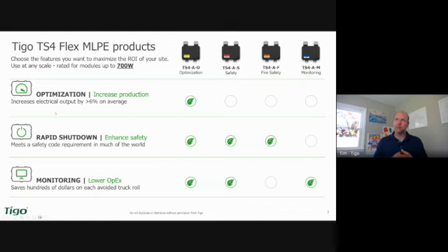That's the ability for each module to produce at its own peak performance, right? Sometimes a system will be installed in a string. If you have an inverter and let's just say 30 modules, you may have 3 strings or groups of 10 modules apiece. What can happen is when a single module is impacted by shading, or degrades over time, or gets heavy soiling, its efficiency will be reduced relative to the other ones on the string, and that one individual panel can bring down the entire string. By having optimizers, each module can produce at its own independent maximum production relative to the other modules on the string. And by doing that, on average, we see 6.6% more electricity by having optimization on a system.